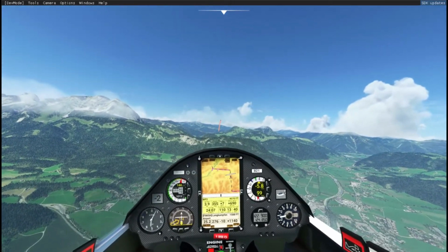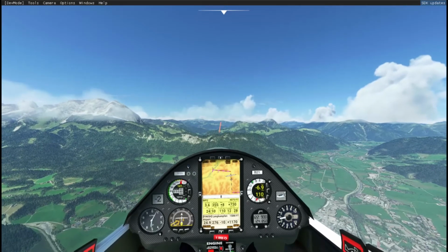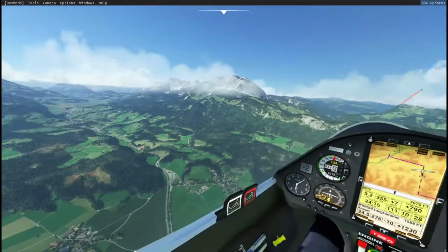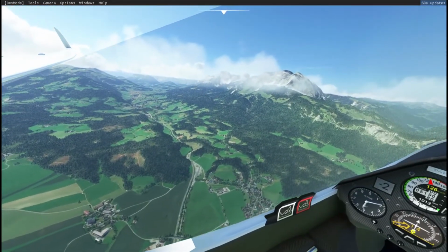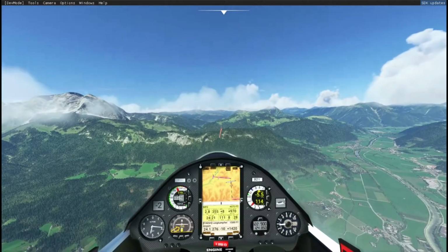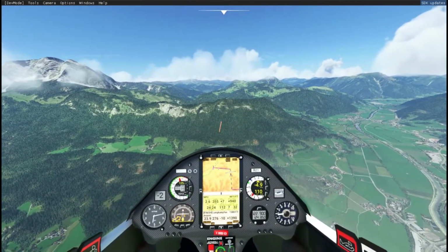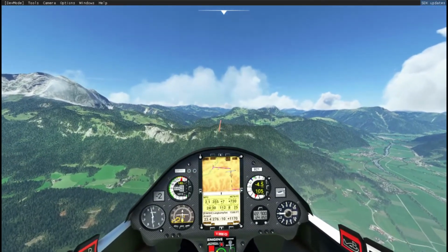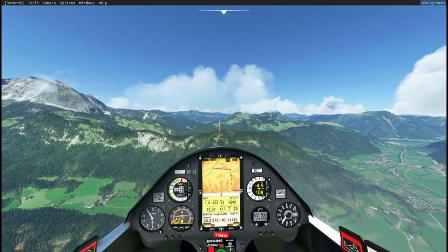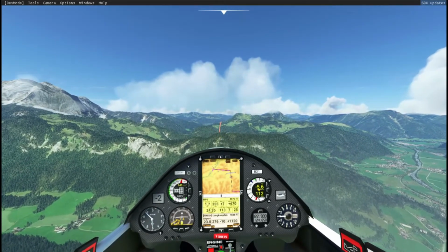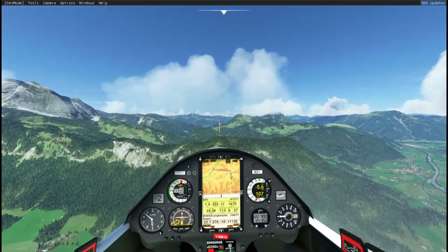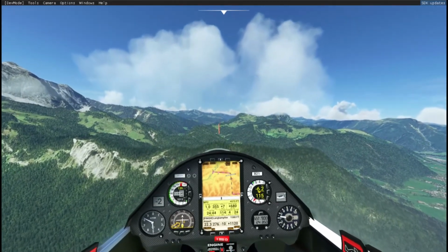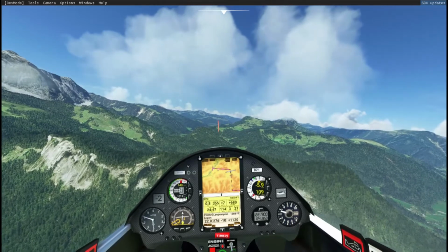Okay, so we're doing fine here. We've still got 1,200 feet arrival height, if that's enough. That was my calculation. Not my calculation, that's my guess. There we go, we'll be going across that one. 7 kilometers to go. This leg we've got a 7 knot tailwind, which is great. And then we'll have, what will we have? We'll have 22 kilometers to go. The pilot's handbook says the ballast could take 4 minutes to dump.